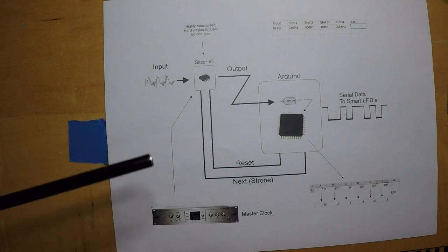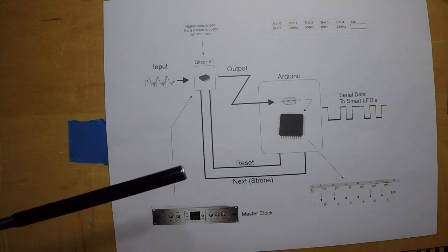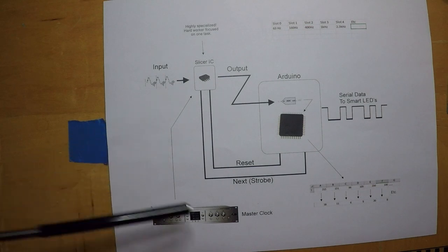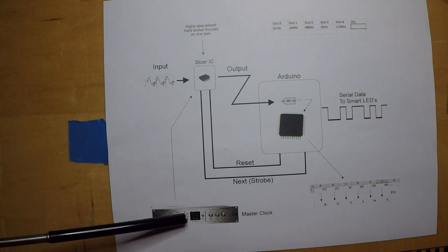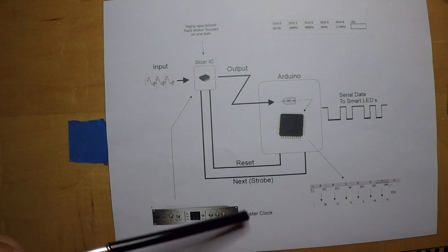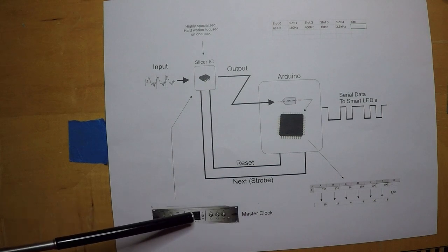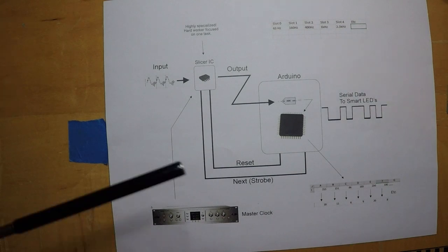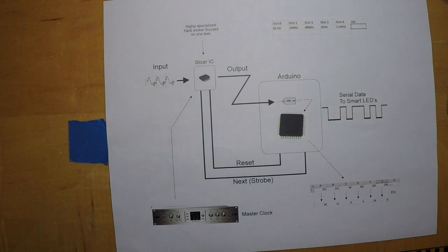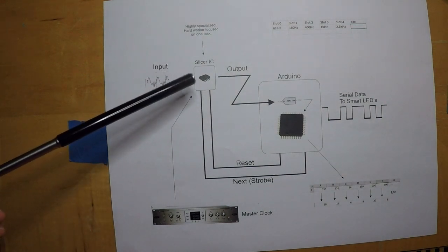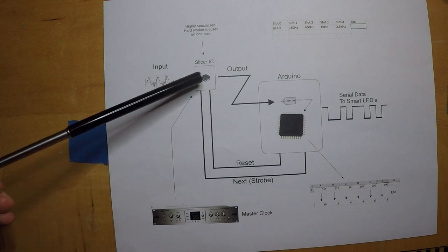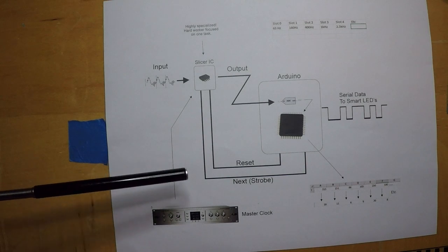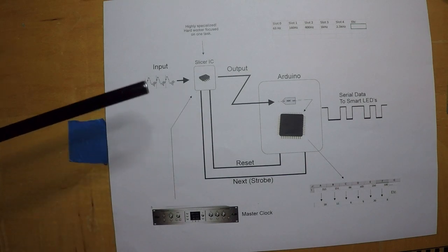But if you looked at my first video, you should have observed that I was using a reliable clock source in that video. I was using a function generator, something like this. Now, of course, we don't want the expense of a full function generator for something as simple as this. So on my board that I'm developing, I'm putting in an IC that is programmable, and I can generate very steady and robust clock signals.